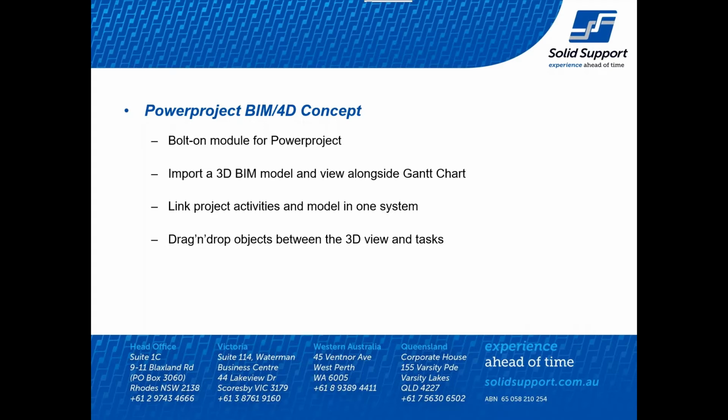Now we will import IFC files. Those IFC files can be created from all the main 3D packages, Revit, ArchiCAD, and so forth. It allows you to link the activities in the model in one system so you can visualize it. So you're not having to export information from Powerproject and import it into another system. We do link with other systems out there, the other 40 systems if you wanted to, but you can do it straight in here, and the planner can do it in their own way.